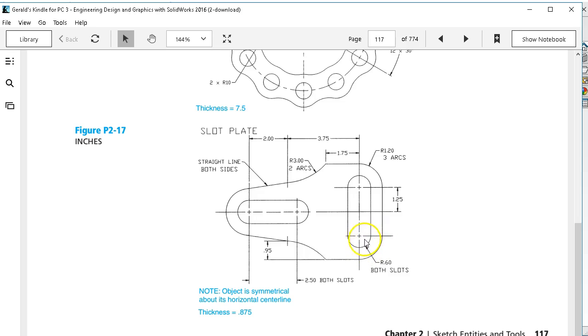We're not really given dimensions, so based on the center marks, what would that be, the 1.25 and then the center at the location. So really we could build this from either end. So we would either pick the origin to be at the midpoint of this line, or possibly at the center of the arc and the slot. All right, so we'll generate the outside perimeter, going for half of it, mirror it over the horizontal center line, and then generate our slots.